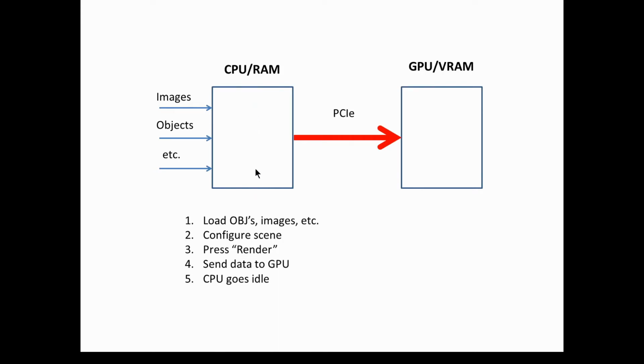At that point, everything's all set, and the CPU then takes all of the pertinent data from that scene that's going to be needed by the GPU to render it, and sends all of that data via the PCIe bus, which is a fast serial bus on your motherboard, to the PCIe slot where the GPU is residing, and it fills the VRAM, the GPU VRAM, which is kind of like system RAM on a GPU. It had already allocated that RAM previously, so it fills the allocated RAM with all of the scene data, and once that's all full and ready to go, the GPU goes through all of its calculations to do the actual render.